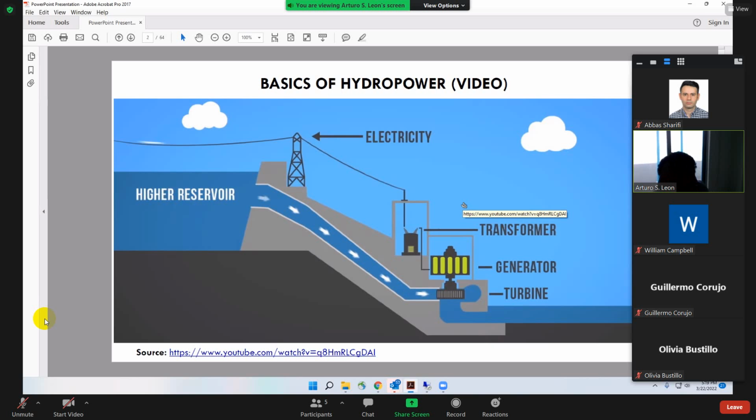According to the literature and according to experience, hydropower and nuclear power are the most stable forms of power because they are pretty much constant, right? But actually, hydropower is even better than nuclear. The reason is that in nuclear power, if you want to start the power, it takes time, right? You cannot just set up the nuclear power in 1 minute. You need at least 1 day because you have to do the setups gradually.